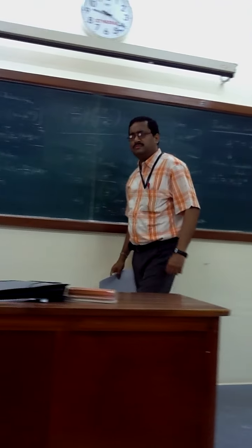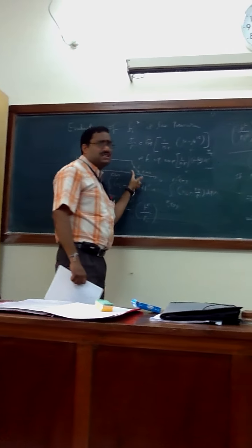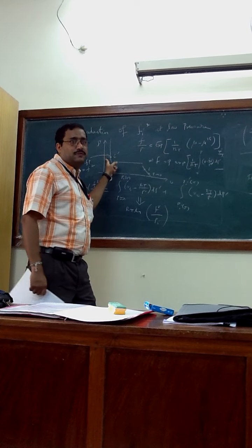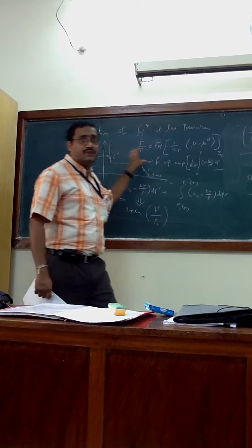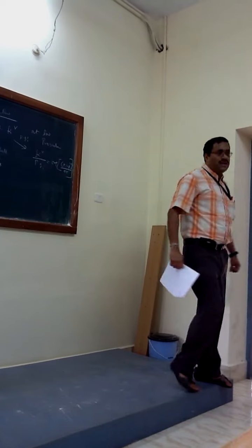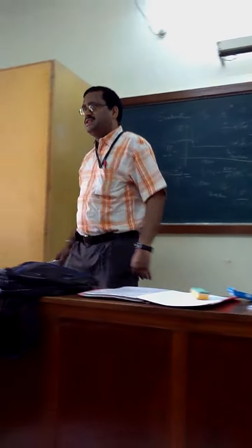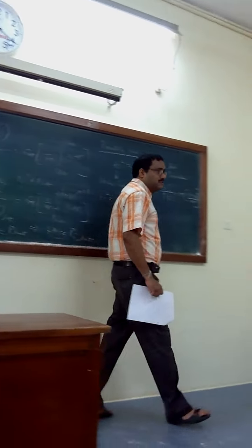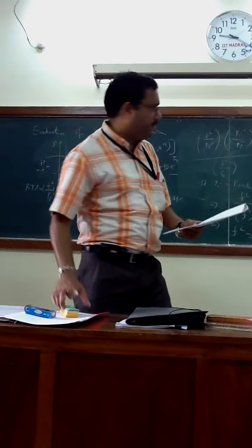So that's the way you have to estimate the fugacity. Vapor phase is very straightforward. For the liquid phase you have to add the vapor phase and then the liquid phase, and that's how the Poynting pressure correction comes. The Poynting pressure correction will not come for the vapor phase, only for the liquid phase. And if it is low pressure, then it is possible to prove that the pure component fugacity Fi star equals Pi sat. Okay, so once it is fixed,